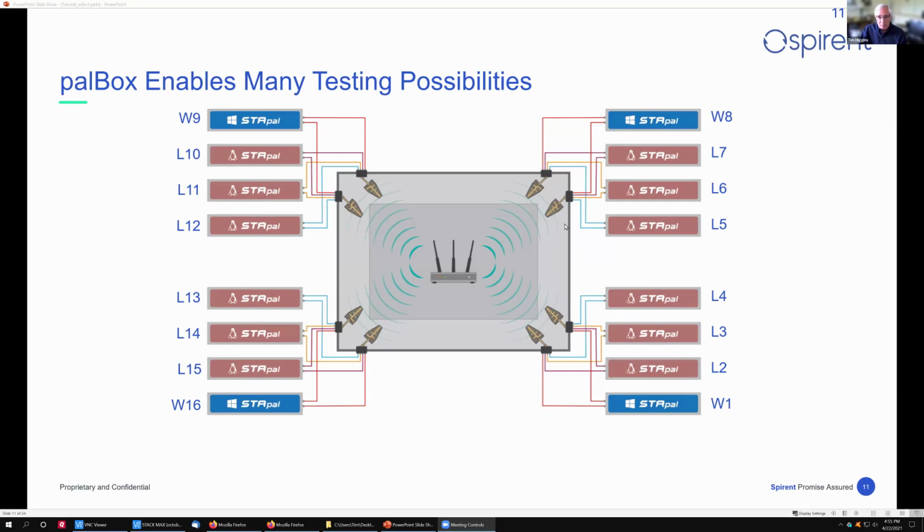Basically, you have the spatial diversity so that if the access point under test has MU-MIMO capability, that should be able to come into play. So we'll come back and look at this to see what part of this we're going to use in a second. Oh, and by the way, not shown in this diagram are the attenuators between the groups of 4. Basically, there's an attenuator channel behind each of these antennas. So each of the groups of 4 can be set at a different distance, have a different path loss introduced. So you can play with that. It's another factor in the test.